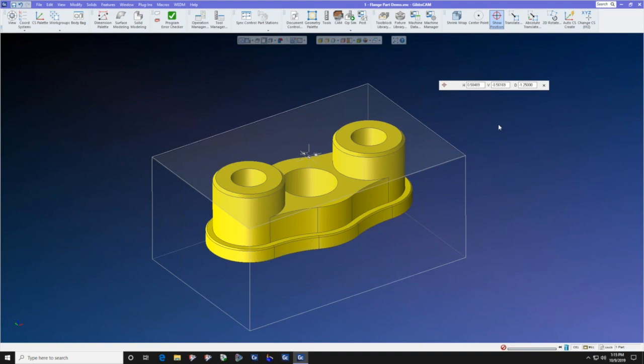You certainly will want to look at your paper drawing that comes with your part because it tells you more about the GD&T, the tolerances, and the method by which they want you to generate and tolerance the holes. They may want it bored, they may want it reamed, they may simply want it drilled.